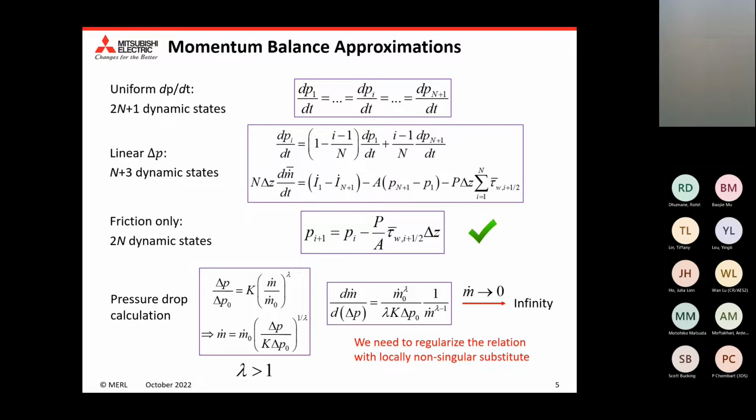Very nice talk. I was wondering, during the compressor shutdown period, do you really set the compressor speed to zero? Can Modelica solve the zero mass flow state? I think so, because with the stream connector, previously we did not do that, but I made some changes to the compressor model so that now we can do exactly so. Now it's very small, so we can do that.